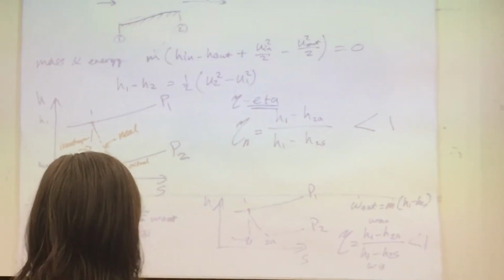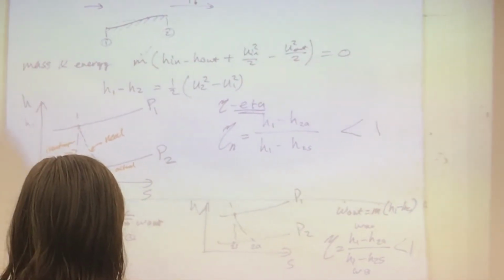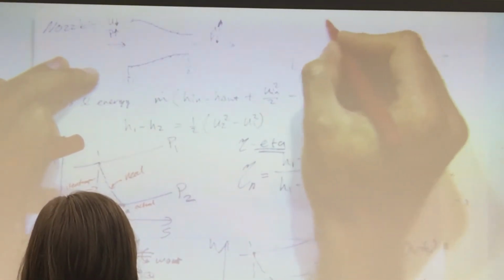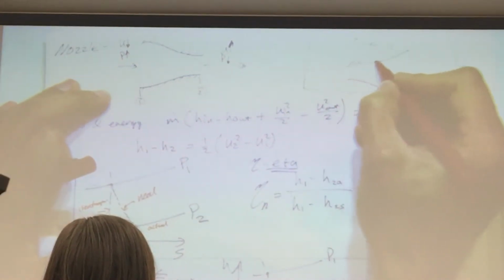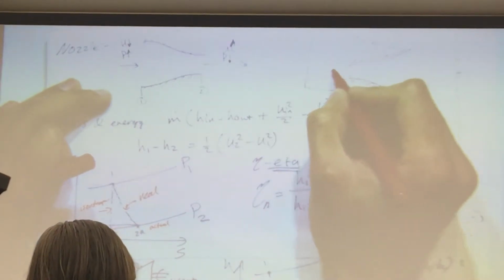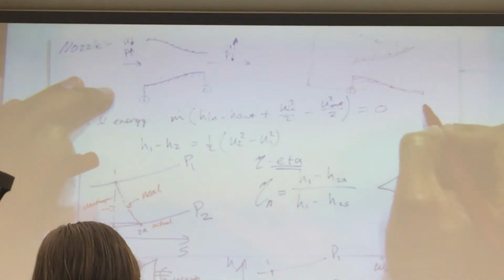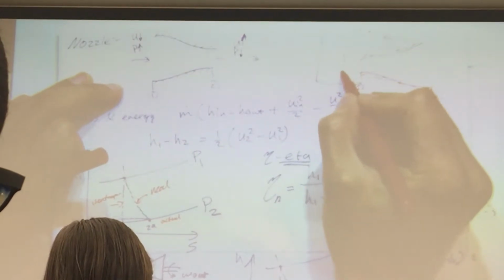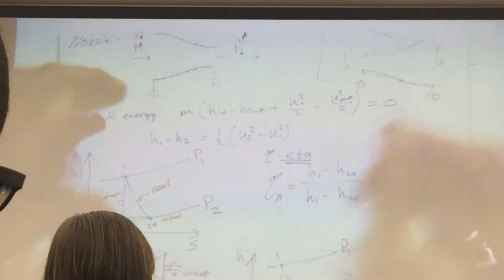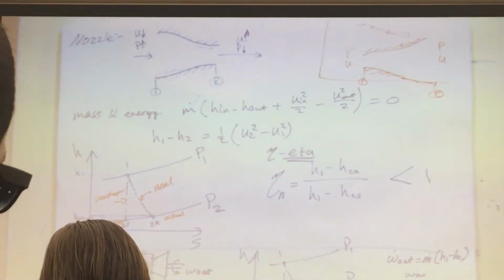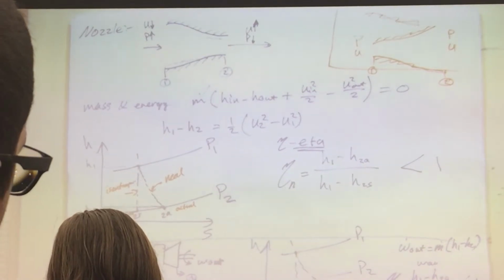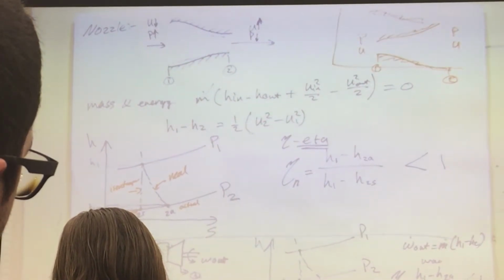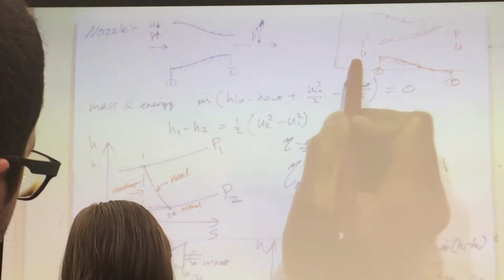Same principle, we applied it for, actually before we do that, well, what if I have a diffuser? You have some diffuser right here, you have some station 1 right here, some station 2 right here. What happens to pressure, velocity, pressure, velocity? I told you to use the garden hose as an example, so you already know what happens with a nozzle and subsonic flow. What happens for a diffuser? What is pressure upstream versus downstream? Which one is higher? So it's pressure versus velocity.